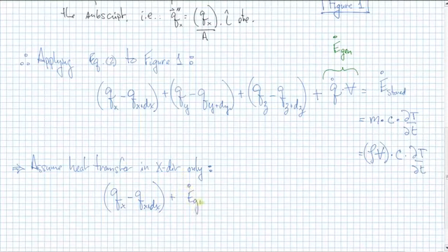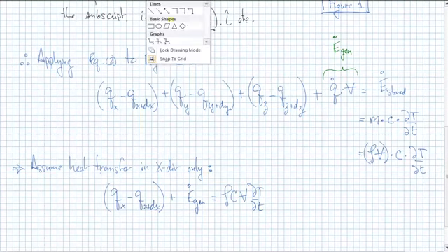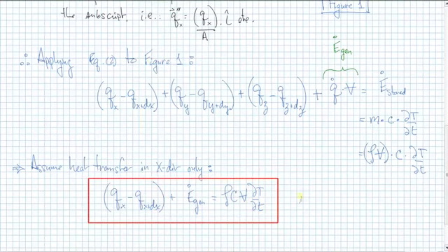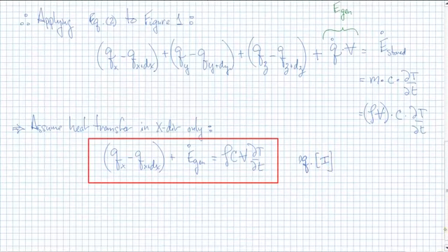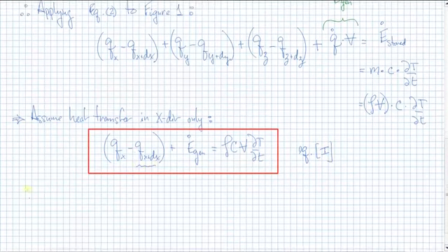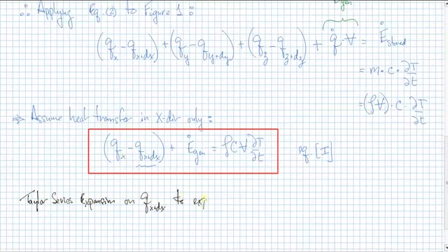That's the main equation. So our goal here is to get rid of the q's. Okay, we don't a priori necessarily know what the q's are. We want an expression that expresses all this in terms of temperature only. So the first thing we're going to do is express the whole Q sub x minus Q sub x plus dx by doing a Taylor expansion on Q sub x plus dx specifically. So remember how that works.